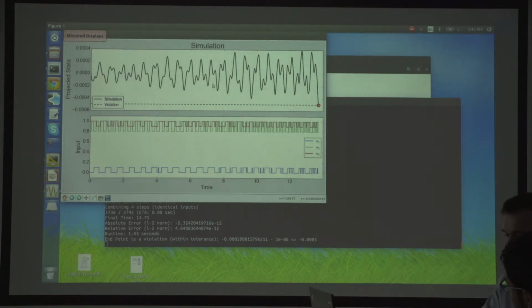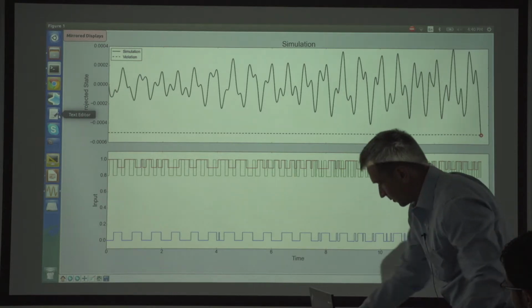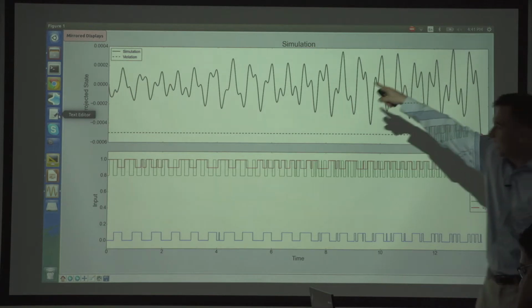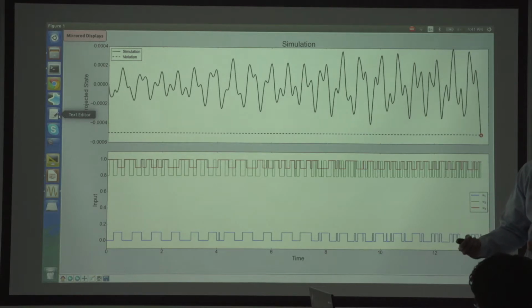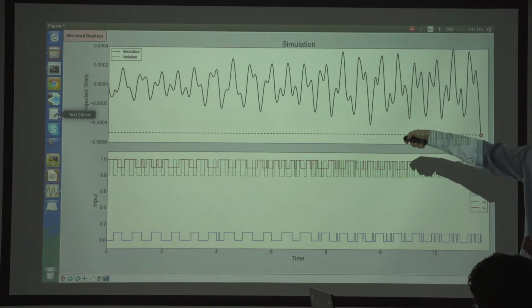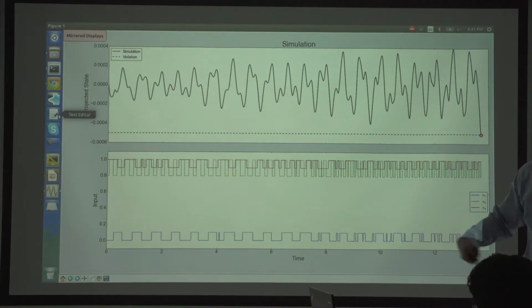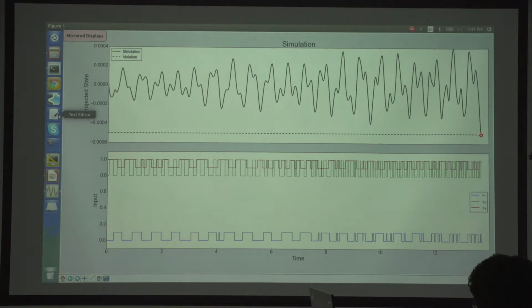So actually running the counterexample took probably about a second as well, but this is what the behavior looks like. So what is this? This is time on the x-axis. The y-axis on the top here is the projected state. So I mentioned the safety property is that one of the outputs is bounded. The output is a linear combination of the states. So initially you start at this state, and then the output will change over time. This is the violation that you're trying to avoid. When you ran this system from the proposed initial state and using the inputs that the tool output using a high accuracy simulation external to HyLAA, you got this path through the system, and eventually you reached a state that was unsafe.